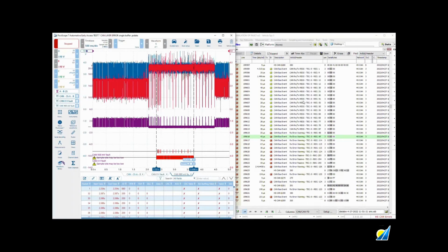And you see here, we've got receive error counter 255. When it gets to that level, that is what they call bus off state. So that node, or nodes, are off the network and are prevented from transmitting. They are isolated. Normally for those to be restored, it's a case of removing the power supply, ignition on, ignition off. But for some reason here, that did not happen on the road, because this was a momentary event, quite lengthy in terms of CAN, 2.5 seconds.